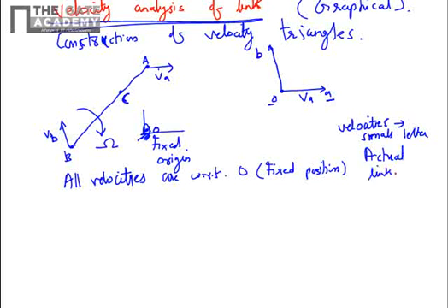The actual link position, the spatial position, the coordinates in space where the position is, will be in capital letters. So in this velocity diagram, you see small a and small b. Small b is the velocity of B relative to O, that is the fixed link. This is VA, the velocity of A relative to O. Then if you connect these two points, B and A, this will give you the velocity of A relative to B, VAB. This will give you the relative velocity.